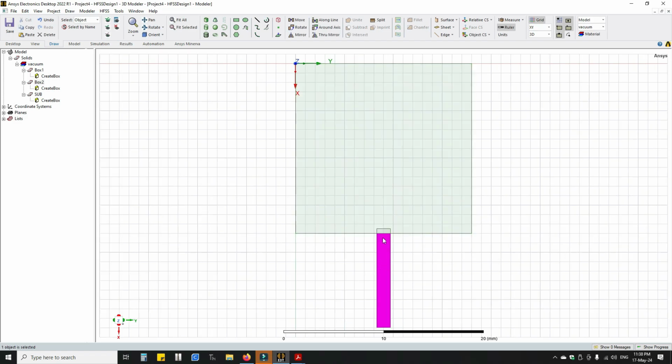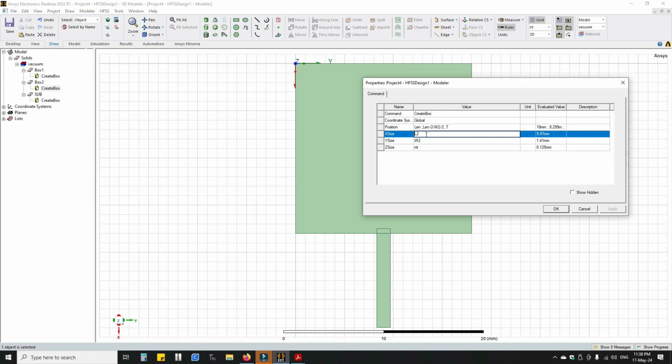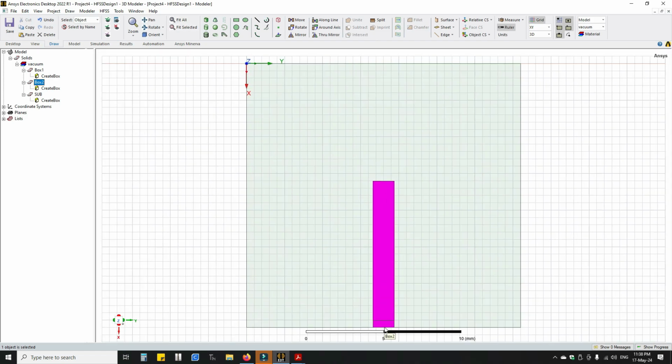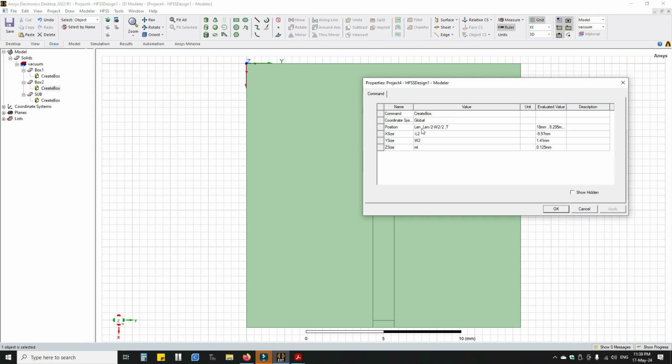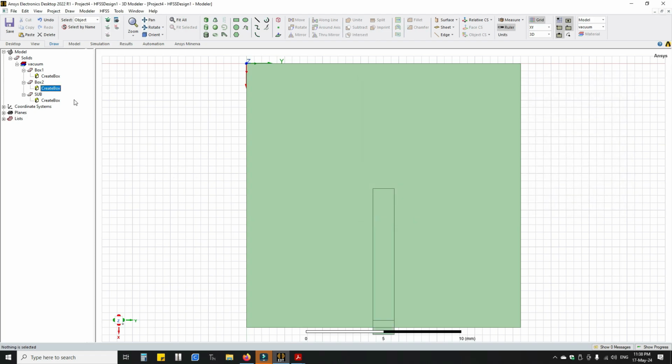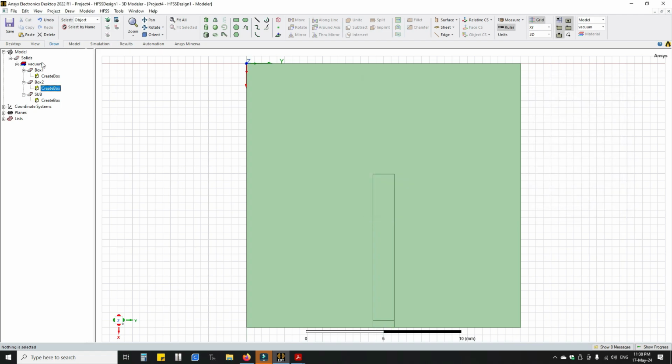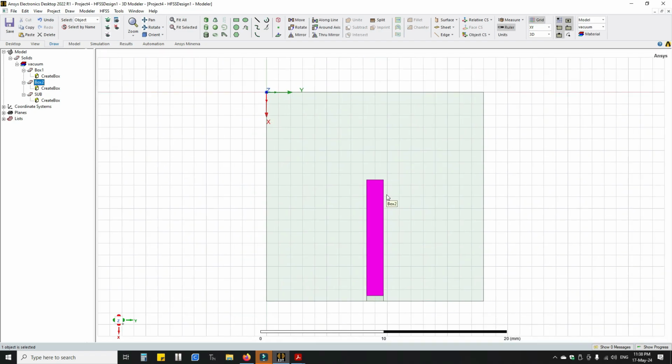Now we are going to add this feed line on the top of this L5. For that, put L2 and put a negative sign here. But unfortunately it started at the end of the substrate, and our intention is to place this on the top. That's why add this length before the X. This is going to start at the top of this entire structure.